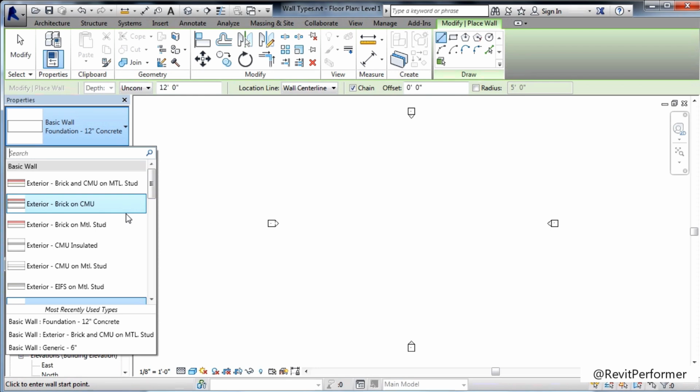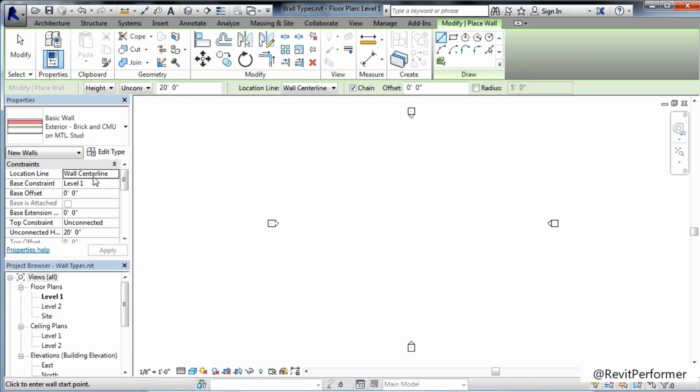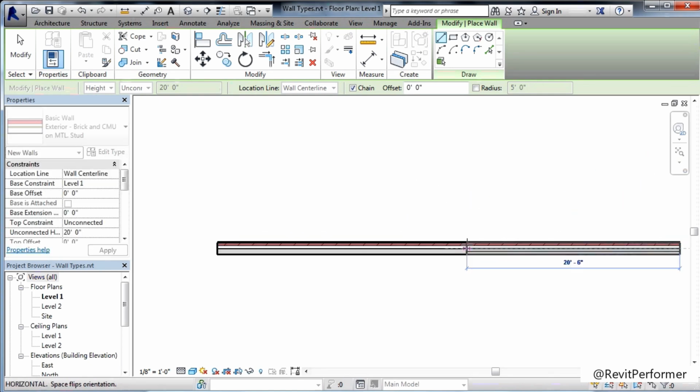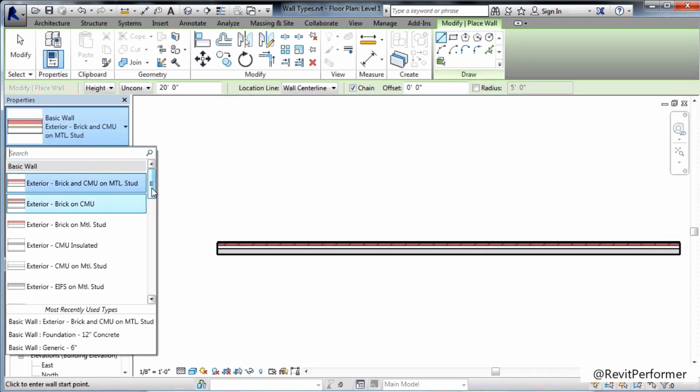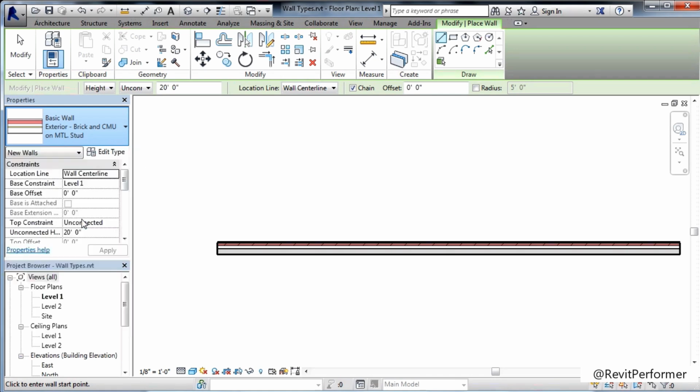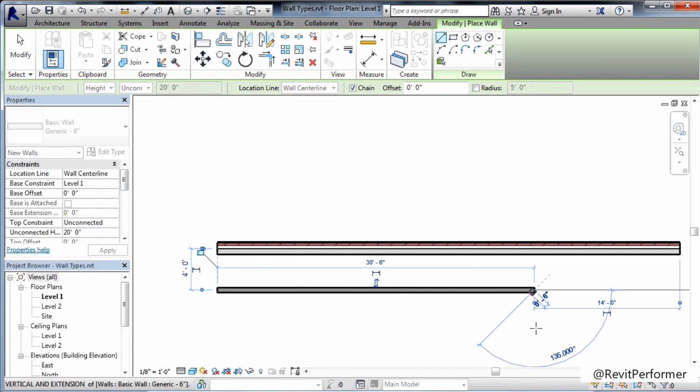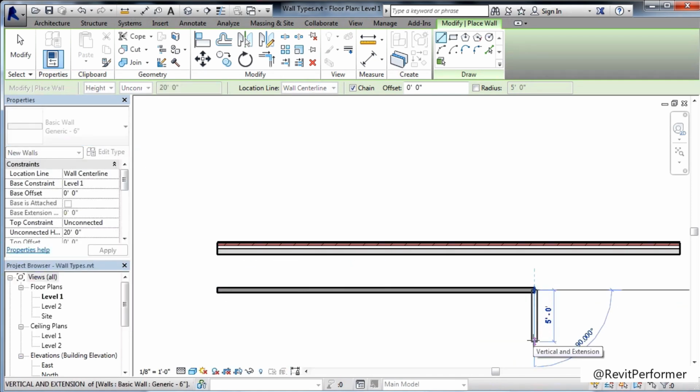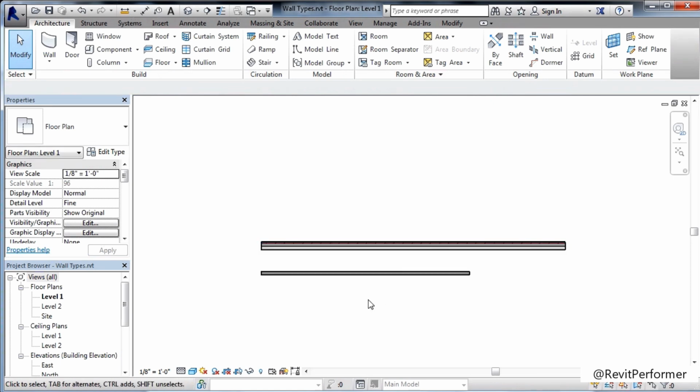Finally, if you want to draw one wall type versus another wall type, all you need to do is select one of the wall types you want to draw off your type selector list, and then click and click again to draw in that wall type on your screen. If you change your wall type to a different wall type on the type selector list, click again, and you'll draw in that type of wall. And finally, if later on you want to switch out one of your walls with a wall of a different type, you can do that too.